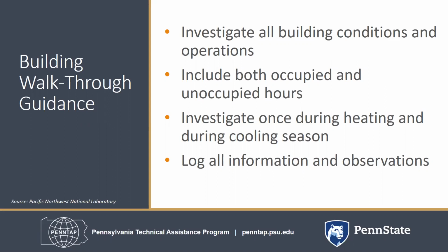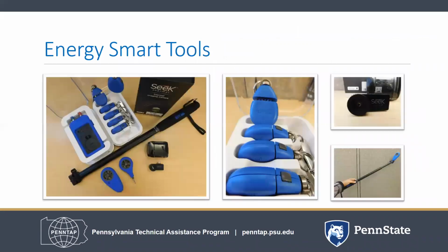There are low-cost energy tools that can help you identify opportunities during the walkthrough. A Seek infrared camera for an iPhone or Android phone will help you detect hot spots or heat loss depending on the season. There are also airflow meters that help measure the airflow and detect leaks. Also, a simple trick for the average height human: pick out a selfie stick with buttons on the handle so you can extend your camera phone plus your energy tool of choice into a higher, hard-to-see place without too much fuss.